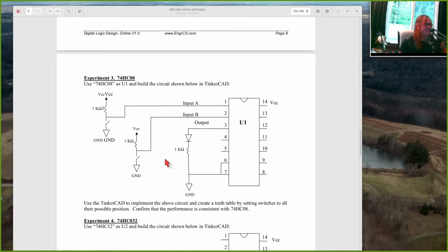And let's come back to our circuit and take a multimeter and hook the negative end of the multimeter up to ground, and then take the positive end and just put it into whatever hole is connected to pin 1 here. And put your switch in your position where A is 0. And if you measure the voltage, you're going to see 5 volts instead of 0 volts. And right there, that's a huge learning moment.